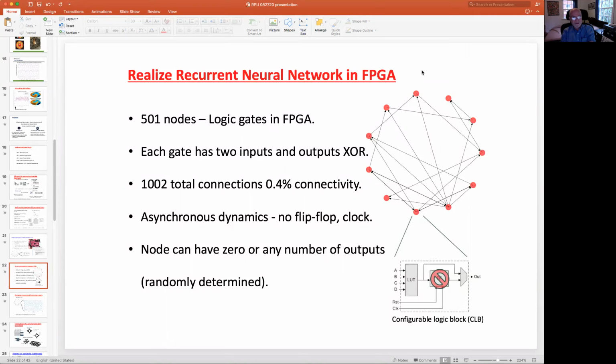Again, it's asynchronous updates on this, so there are no clocks, and there's just information freely circulating on this large graph of nonlinear elements. Now, in this particular case, we didn't put any input on the reservoir. We were just curious what the dynamics of the reservoir would be freely running with no input data. This was with a mindfulness of what we've seen in the past, where arrays of logic gates can have autonomous dynamics of their own. And this network very definitely did that.